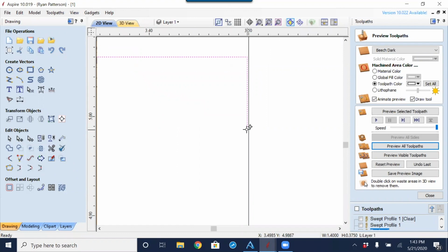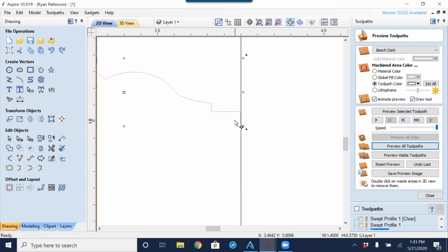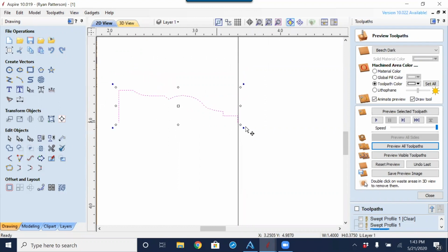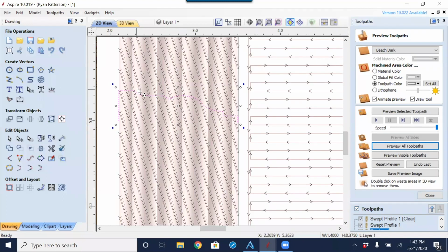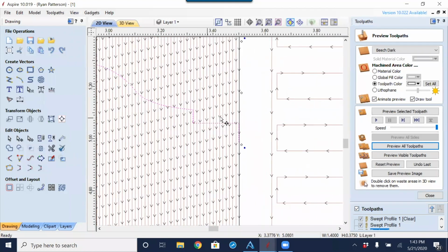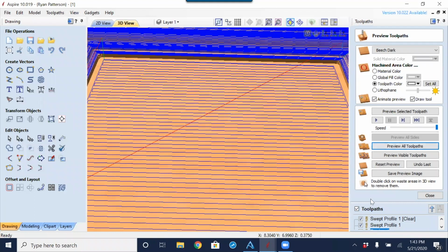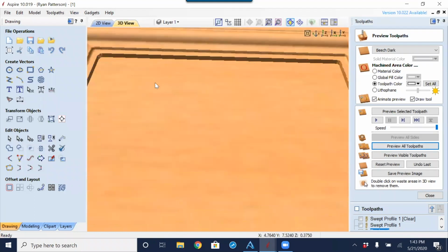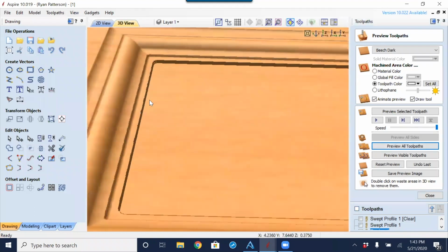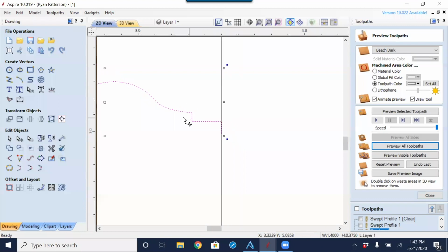So that is where the bit in the profiling toolpath, and that's where the 3/8 is coming from, even though the toolpath for the profile is not coming out any farther here. So if we did want to have our pocketing toolpath not have this gap here, we just wanted it to flow straight out along at the same level as this line here, we could do that.